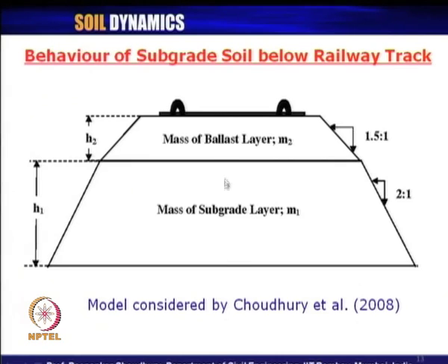And how to design this subgrade layer, you know, using the CBR values, etc. So, the design technique, everything under the static condition, is very well known. It is similar in the case of pavement also, in the case of runway also. So, the same model can be used for the analysis of pavement, also for the analysis of runway, because those are also subjected to moving load on the ground surface like this. So, we have shown in this case only the application related to railway track.